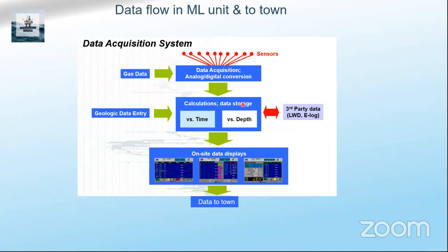And then there is some computation, like for example, the ROP. There is no sensor called ROP. Many beginners in the industry get confused about where the ROP sensor is. There is no sensor called ROP. This is a calculated parameter. I have a slide on that as well: what the calculated parameters are, and what is the exact data read from the sensor.